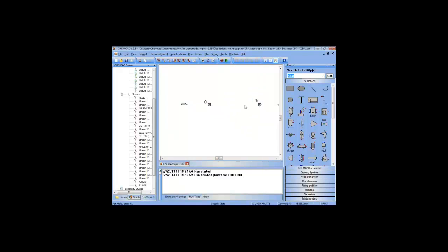If I had specified a closed loop and pressed run, every unit operation in the branch would have unusual numbers. This would fail to converge. Stuart had a yellow light for a convergence problem earlier. I might have a red light on all of my units fail to converge. It's very hard to go through all of those units finding the problem.